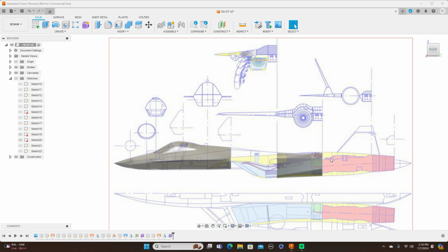So what I'm going to have to do is probably draw formers from these existing ones, make smaller ones, offset this and make a smaller one, and be able to loft from here, surface loft from here to here, and also from back here to here, because this former here, as you can see, the top of it is a lot different than the top of this former, the one that goes back here, and then it gets smaller right back here.